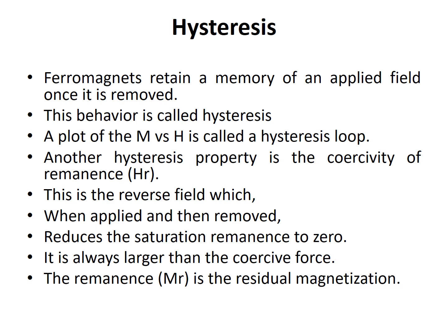Another hysteresis property is coercivity of remanence. This is the reverse field which, when applied and then removed, reduces the saturation remanence to zero. It is always greater than the coercive force. Remanence, represented by Mr, is the residual magnetization that remains after the material is first saturated in a magnetic field and then the field is reduced to zero.